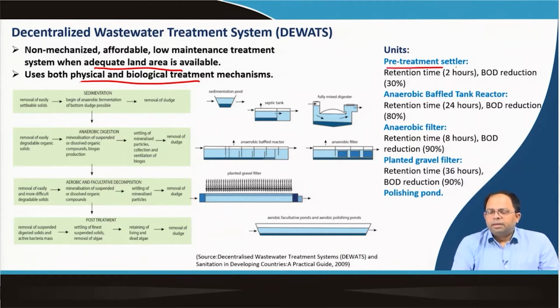One is the pre-treatment settler, that means we allow the sewage to settle. Retention time is around 2 hours, and this leads to BOD reduction of around 30%. So, that means some amount of sedimentation happens, and that leads to reduction of BOD by 30%. Then anaerobic baffled tank reactors. So, we know what is the anaerobic baffled tank reactor. Retention time is around 24 hours, and BOD reduction is around 80%.